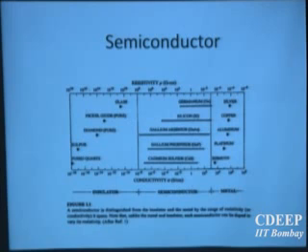What is this combination I am talking about? Let's say indium phosphide. Indium is from the third group, phosphorus is from the fifth group. So it is 8. Silicon is from the fourth group, which also has 2 bonds, 8. So it's trying to match that number 8. So 3, 5, indium phosphide; and mercury telluride, 2, 6. So you can always see a material which forms 8 and therefore can be a semiconductor.